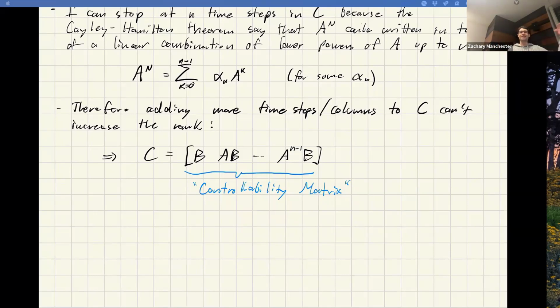So this stuff is easy. You can do trajectory tracking with time varying LQR, i.e. the LTV version where you linearize along a trajectory. You can actually solve nonlinear trajectory optimization problems using what's called iterative LQR, where you basically treat LQR like Newton's method, and you relinearize and resolve LQR to update until you converge. There are multi-agent game theory versions of this stuff called linear quadratic games. There are robust versions of it.